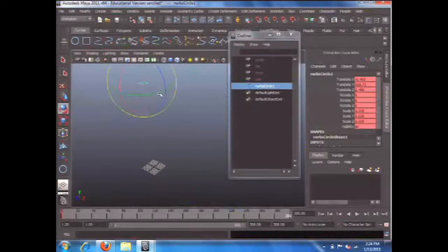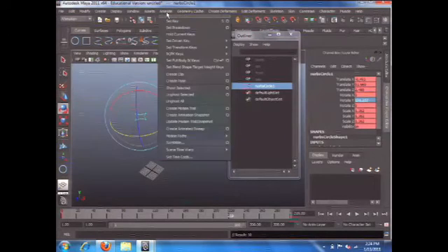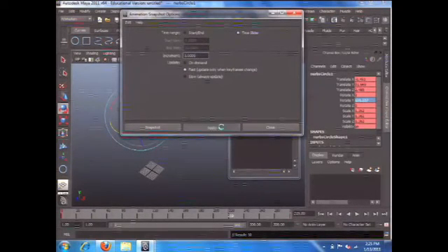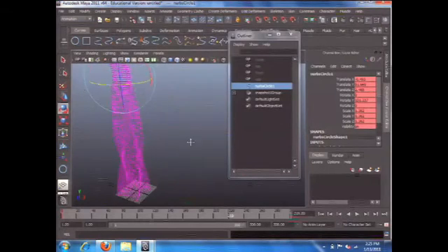Maybe rotate a little bit. You can type a number directly here. Let's see. I want to rotate 180 degrees. All right. So use S keyframe. Now you have animation between these 2 keyframes. Then I'm going to do a snapshot. Same thing as the other. Hit apply. All right. So you got a sequence of curves.